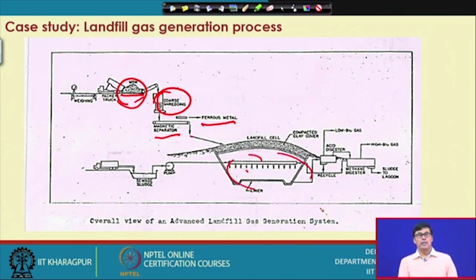Now there is an international sanitary law. The international sanitary law says that whenever you put any kind of organic waste in the landfill, it should be covered with a 6-inch clay layer within 24 hours.